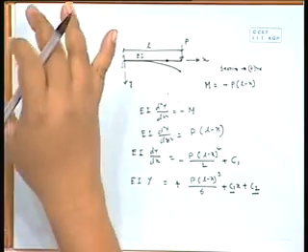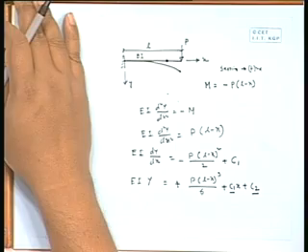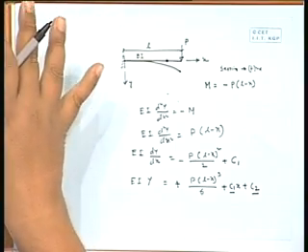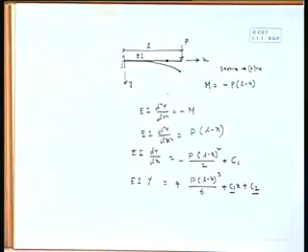So, at the two ends there are some conditions, and those conditions will be utilized. We say it is a boundary condition. Say here this is a fixed support. So, y, the deflection, is 0, plus at this point itself the slope is equal to 0. Not necessarily it will be at the same point all the time. If we have a simply supported beam, deflection will be 0 here, and deflection will be 0 here. Okay.